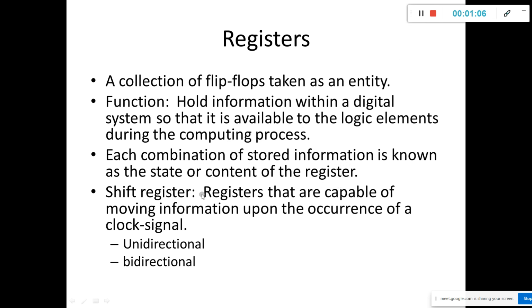Shift registers: registers that are capable of moving the information upon the occurrence of a clock signal. The data or the information can move in a single direction, that is unidirectional, or it can move in both directions, right to left or left to right, that is bidirectional.